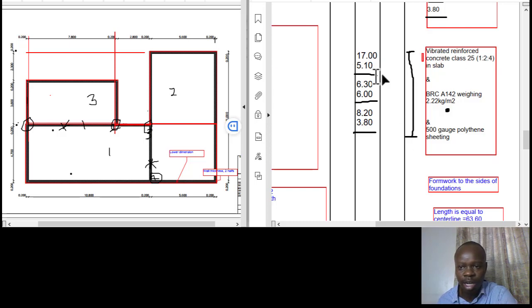In fact, this is even an easier approach. You can use this as the area, okay, and then you now need to subtract the areas for the walls, because also you've already calculated the walling. When you have the walling, just take the total length of the walls times 0.2, or the width of that particular walling, so that you ease your time in terms of getting the exact area of the hardcore.